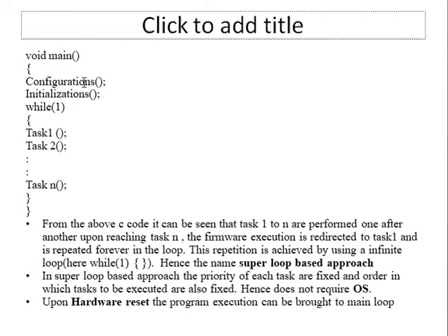So you require those where the clock, it might be related to the clock speed, you define the clock speed, it might be related to configuring your pins. All are addressed first, then inside the while you write the program. Probably you think of it as a first stepper motor program. So you will be having a port initialization, you'll be having its direction set.